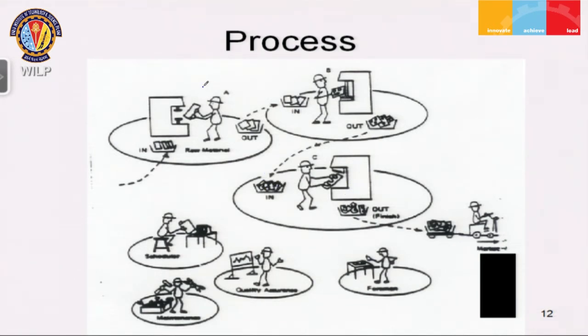So if you really take a look at it, the total time from when we bring in the raw material to the first operation till we are able to take the finished goods, we have the time required to produce one entire batch in the first process, the time required to produce one entire batch in the second, and the time required to produce one entire batch in the third, plus the time that would be required as the delay time, which is when this particular operator has finished this one batch. That is when he will call a material handler to come in and move this material.